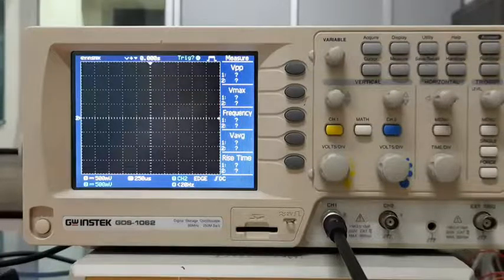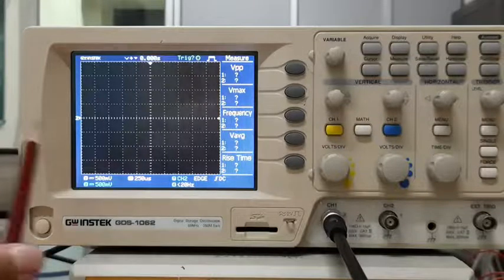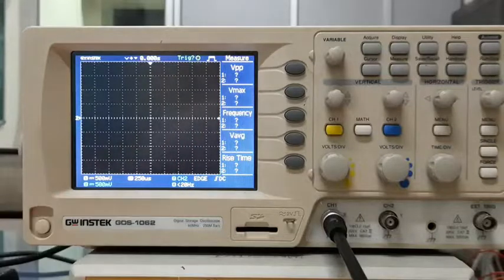So for example, if I have a 1 kilohertz signal, that means its time period is 1 millisecond, right? In 1 millisecond I'll have 1 full cycle, and if I want to see 2 cycles, then my time window should be at least 2 milliseconds wide, right? So here from negative to positive, it's about 2.5 milliseconds wide. So that's sufficient. In fact, we'll be able to see the signal for at least 1 full cycle here. So the ranges are fine, right?